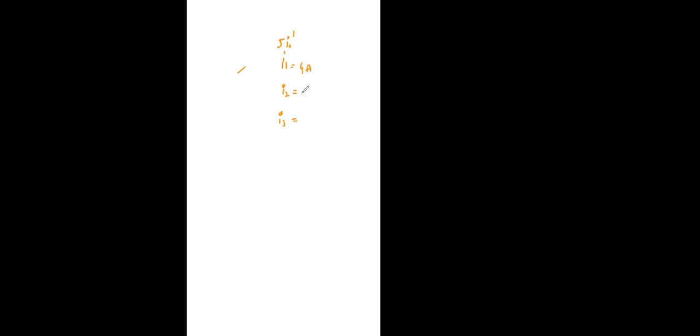Sometimes we use small i's, right? I1, I2, I3. So already I1 is 4 amps. What about I2 and I3? Can I get the equations first? Let us solve. Sir, for loop 2, I got minus 2 I2 plus 4 I3 equals 20.